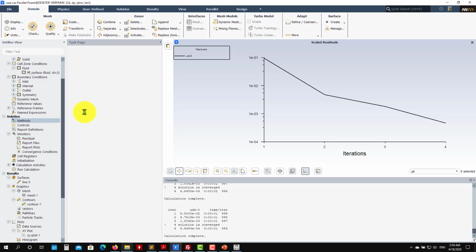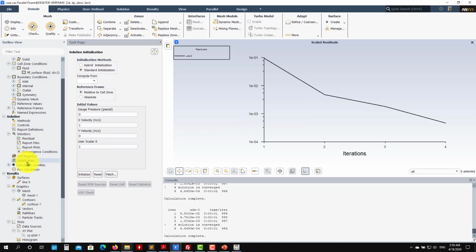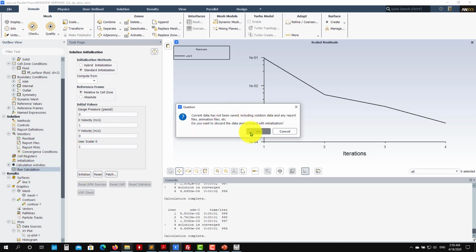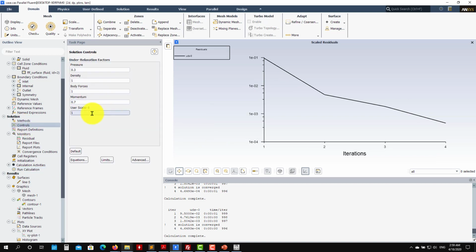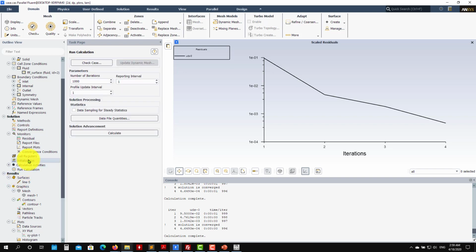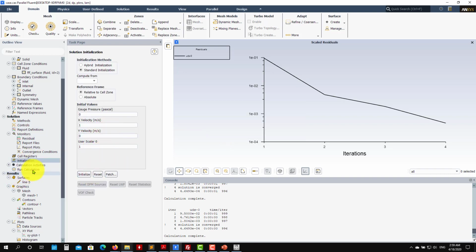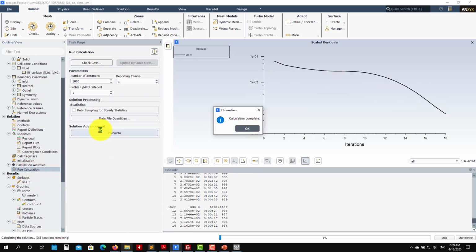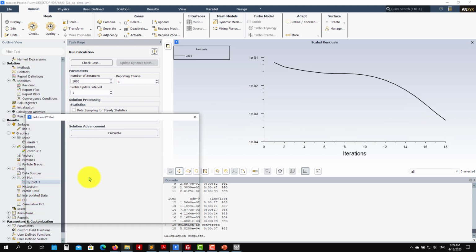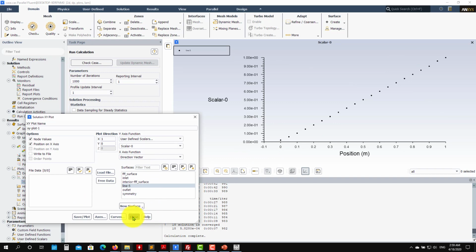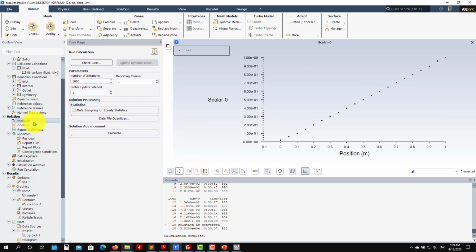Let's go with PISO. Okay, default values, initialize. Those are not the ideal ones. Initialize, and run. Okay, in 4. So probably it's better to reduce this one to 0.7 just to get an idea. Let me go here, PISO, in 18 iterations. So you will also realize that all methods have different convergence rates. This is okay. So usually PISO is something that you would use for unsteady.